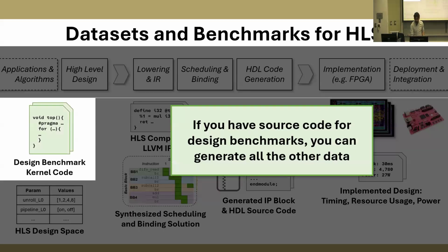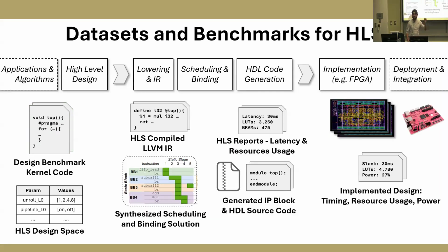Also, when you run your HLS tool, there's a lot of pieces of data that appear. So you have your source code, your design space. The tool will lower it to assembly-looking intermediate code called LLVM IR. It'll generate a schedule of when all the hardware operations happen. There'll be a report. You'll have the generated Verilog, and then if you run the actual physical design, you'll also get timing and resource usage metrics, right? So we want to collect all of this stuff.